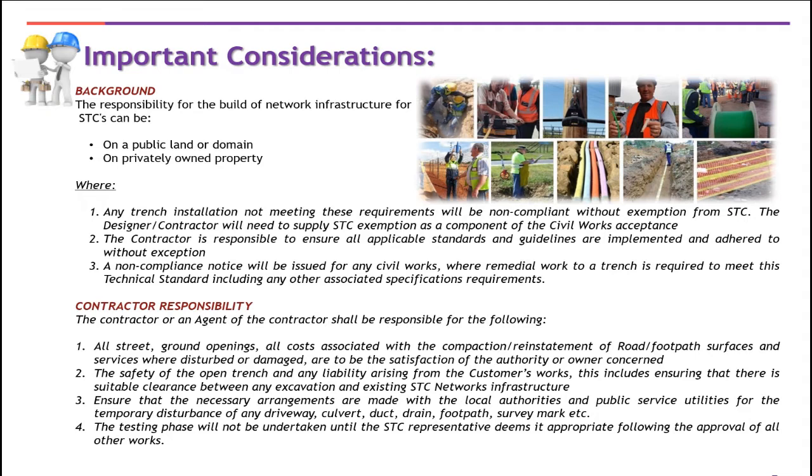The telecommunication standard references require separation between different underground utilities. Any trench installation not meeting these requirements will be non-compliant without exemption from STC. The designer or the contractor will need to supply STC exemption as a component of the civil works acceptance.